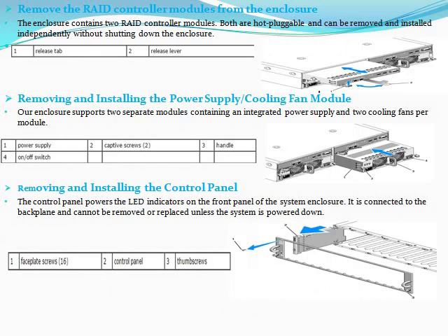Now, removing and installing the power supply cooling fan module. Turn off the power supply we intend to remove using the on-off switch.